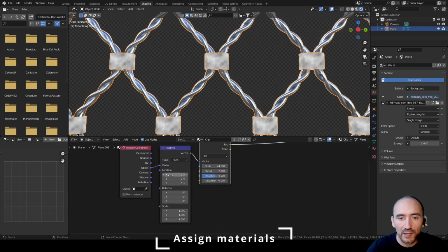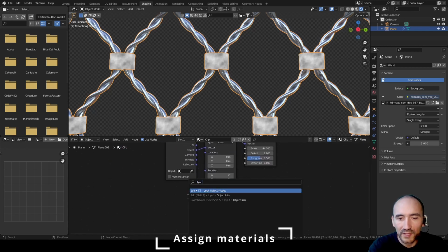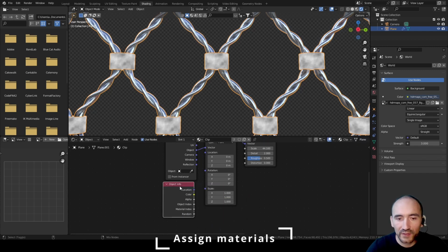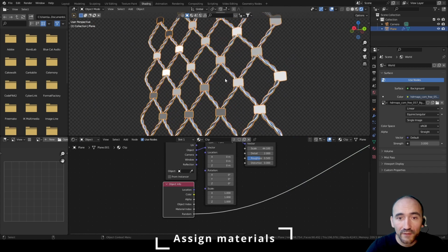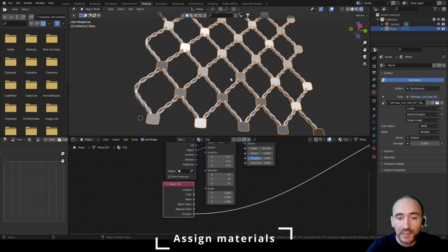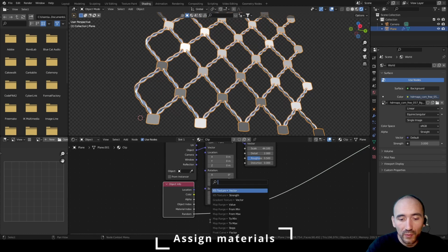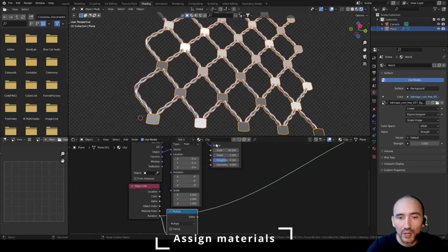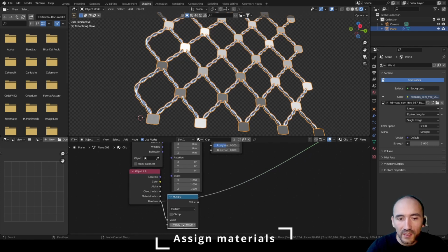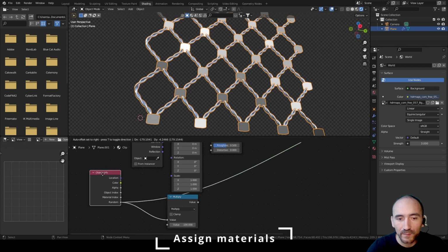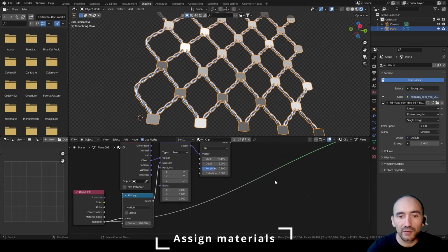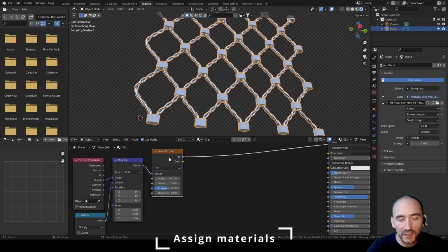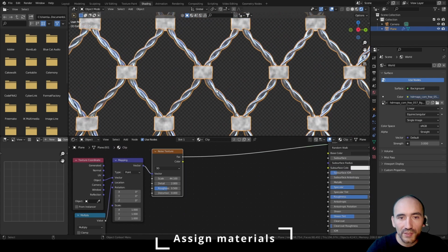So to do this, we can adjust this location with the object info node, and we can see Shift Ctrl click. If we go in the random, you can see we can get a value from 0 to 1 for each clip, and we can use these with a multiply to have more distance between the position of the noise node from each clip. We can multiply these by 100 and link these to the location vector of the point, and you can see if I isolate the selection to the noise, we have a different pattern of the location of this noise texture.